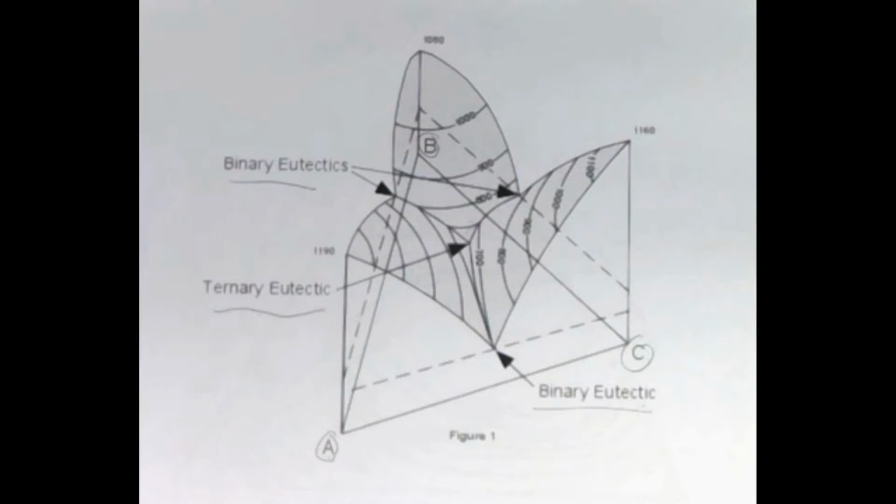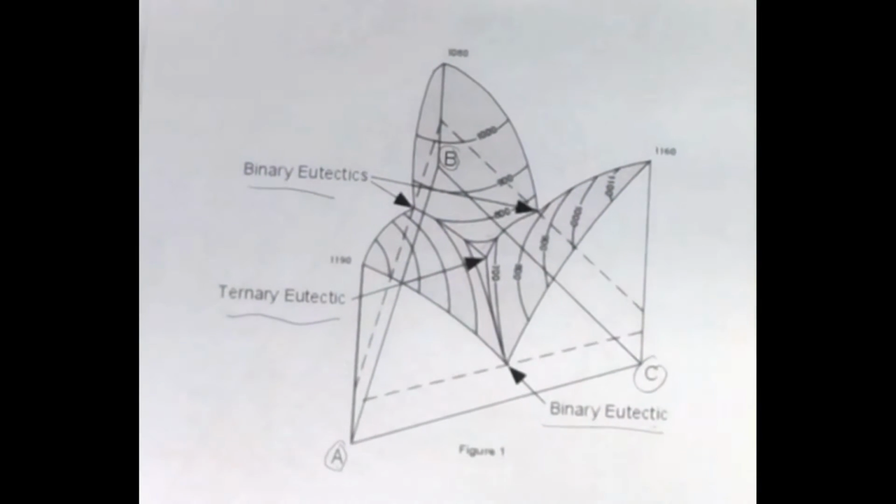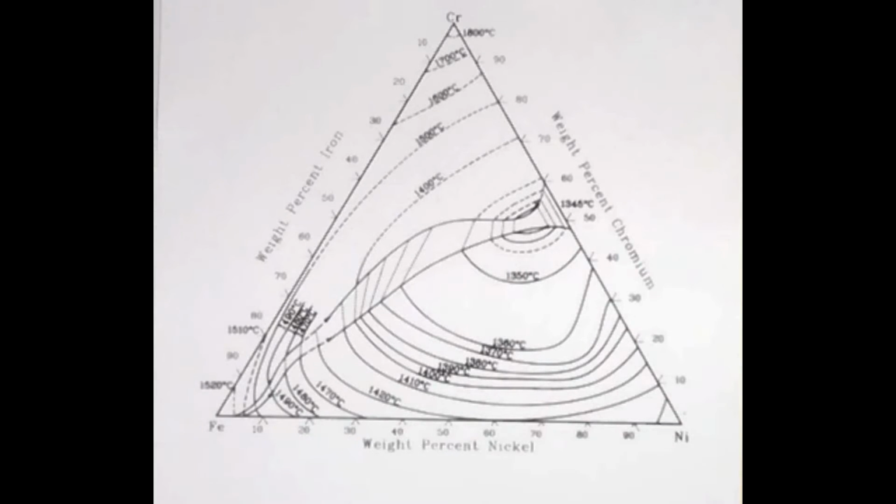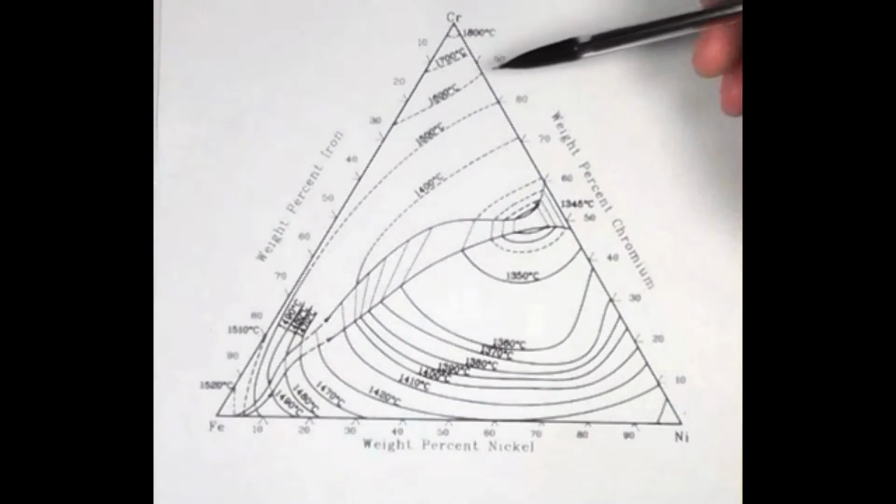This is kind of similar to mapping mountains on a flat map. The 3D version here is the real-life system, but it's very hard to read. So we take the isotemp lines and map them onto a 2D plane. When mountain elevations are mapped to a 2D image, continuous heights are mapped. However, for the ternary system, we're going to map continuous isotherm temperatures.